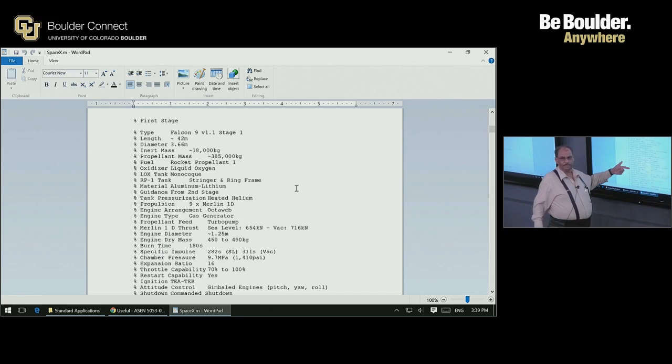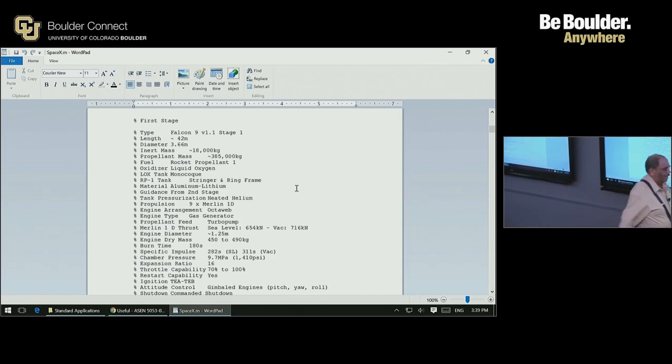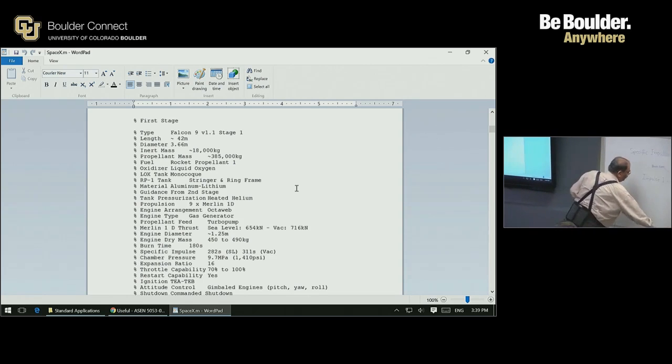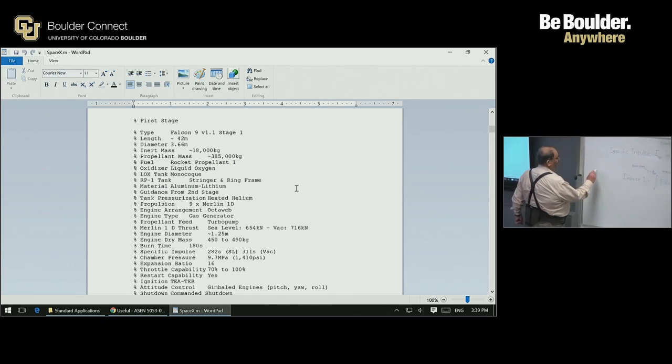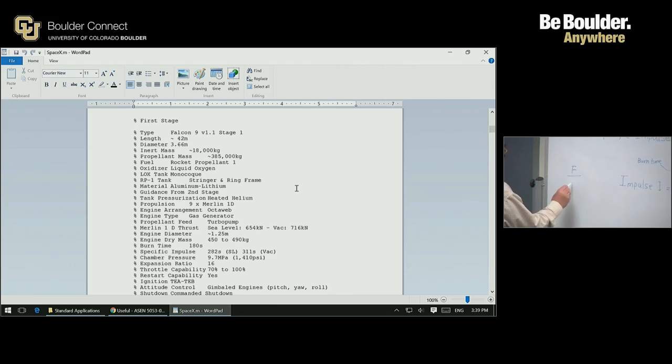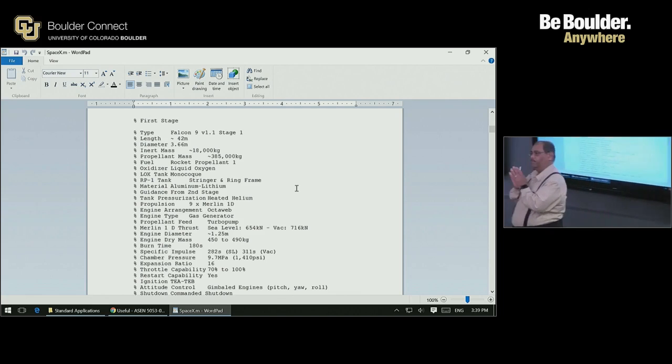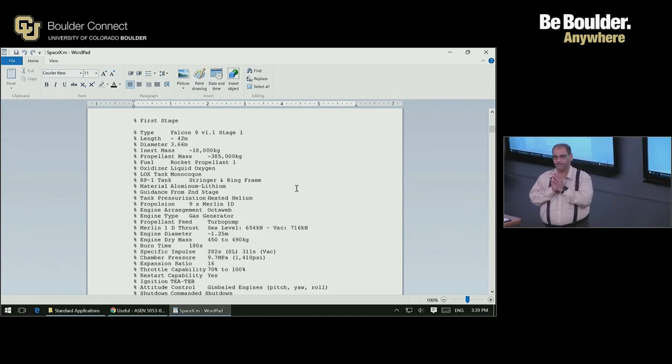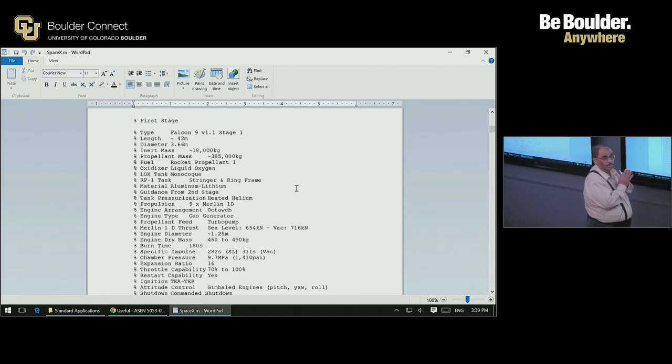Dry mass of the engine, that is of interest, because as engineers, we want to build an engine with as high a thrust weight ratio as possible. Okay, this is the thrust of the engine divided by the weight of the engine, which is mass of the engine times G naught. Okay, please don't make the mistake in this class of confusing between weight and mass. Okay, that's very, very important.